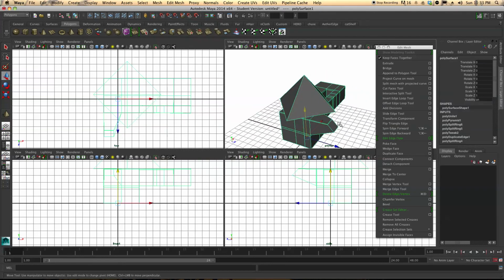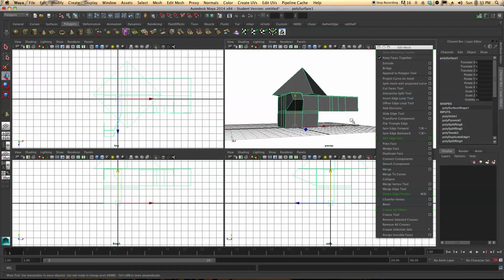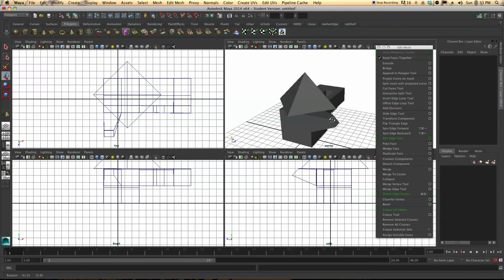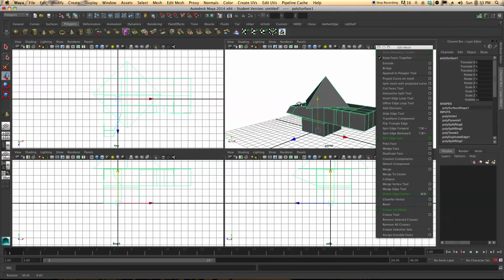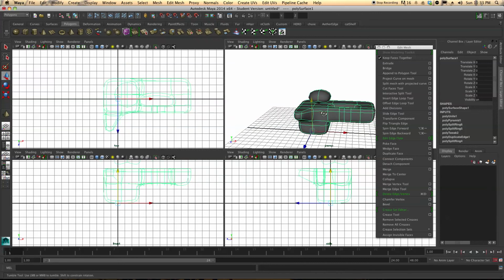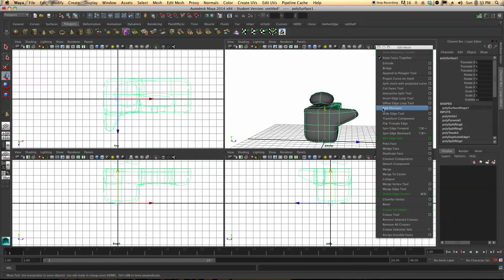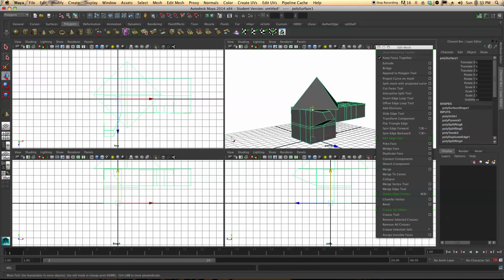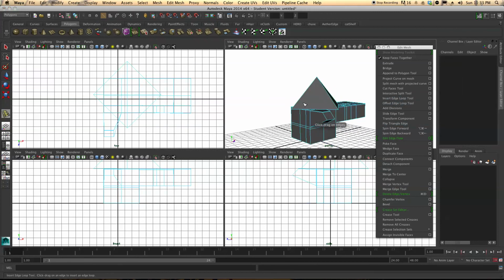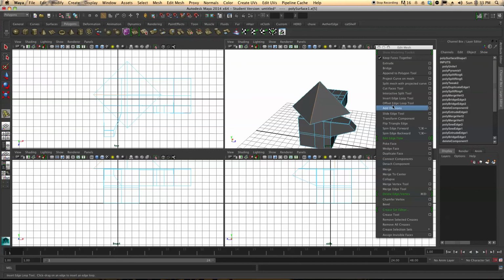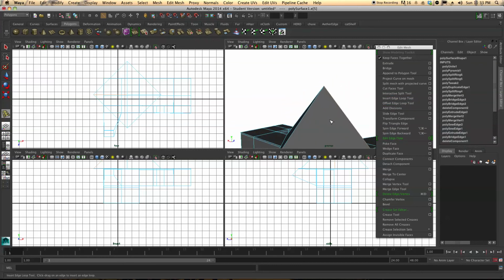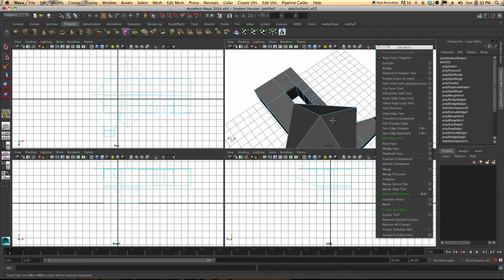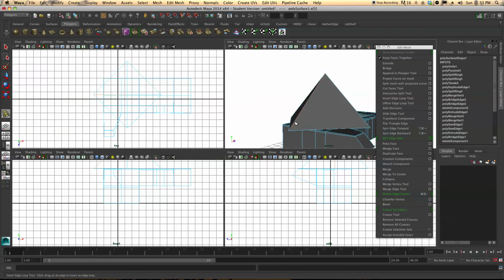Now this is not always going to be something you're going to want to do immediately, but later on you may want to combine multiple objects into one solid prop. It definitely has its uses. And well, that is an ugly smooth preview. So let's go ahead and real quick give it a few edge loops just to maintain its shape. But of course you can't do this right now because, with there being a center point, as I said before, you want to avoid triangles, and this is just a three-sided triangle.